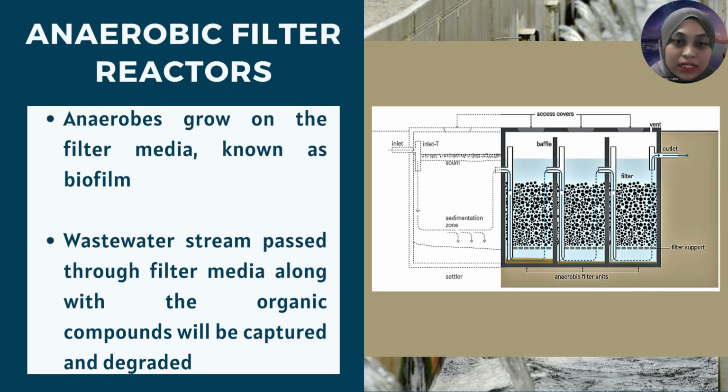The last one is anaerobic filter reactors. The anaerobes used in this system will grow on the filter media, which is known as biofilm. The wastewater stream that passes through the filter media is exposed to the biofilm, and the organic compounds will be captured, digested, and degraded.